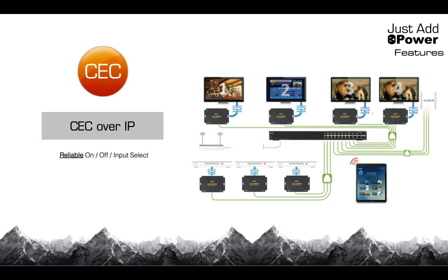We can do CEC, which I know most of the time you stay away from because you get weird things happening that you don't necessarily have real control over. But in our world, it actually works really, really well if we're just turning a display device on and off and maybe selecting the HDMI input. If those are really the only three things we're trying to do, CEC is your friend in our world.